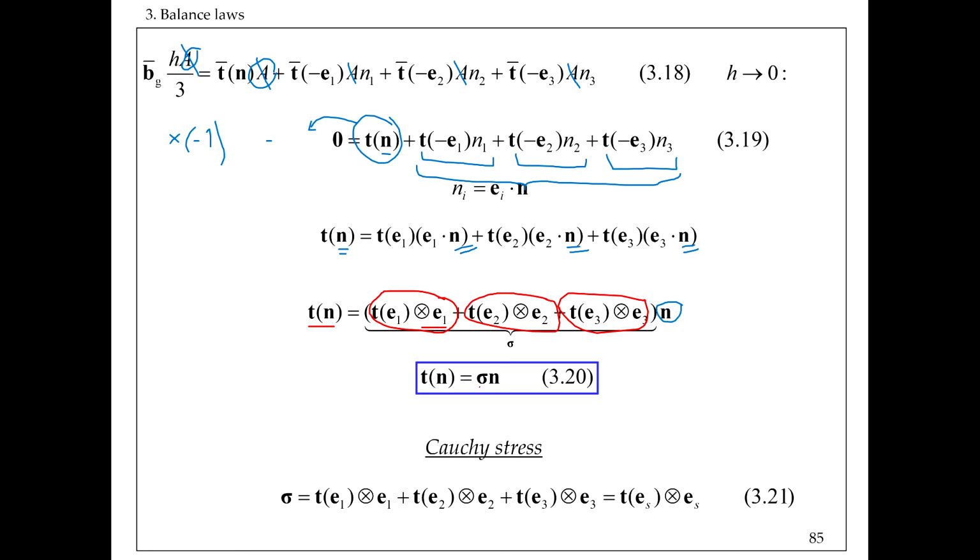And very importantly, while the traction vector depends on how we decide to put this normal, at which angle, for example, in the two-dimensional case that you've seen, different angles would determine that n differently, and then your traction vector on that surface would change, would be dependent on n.